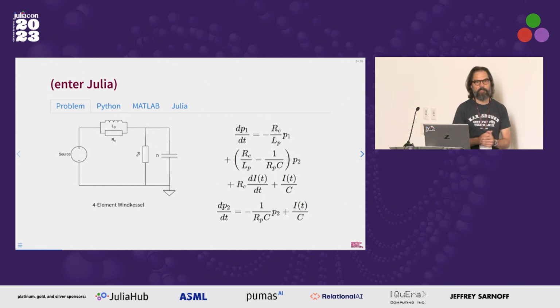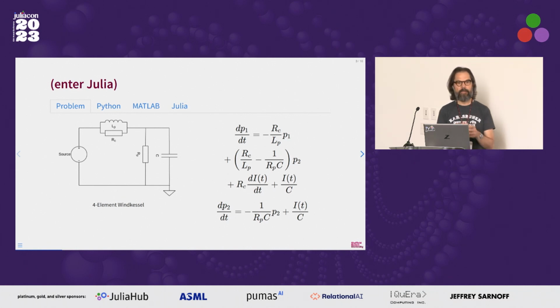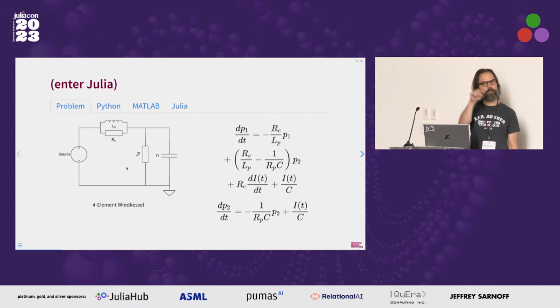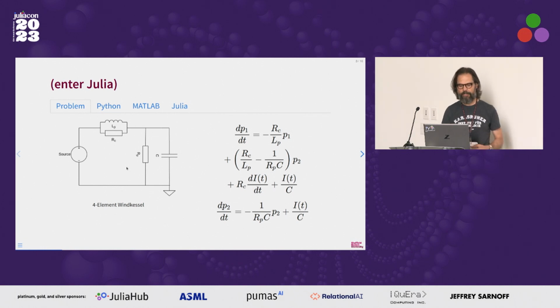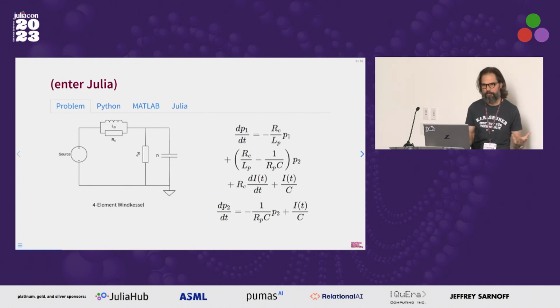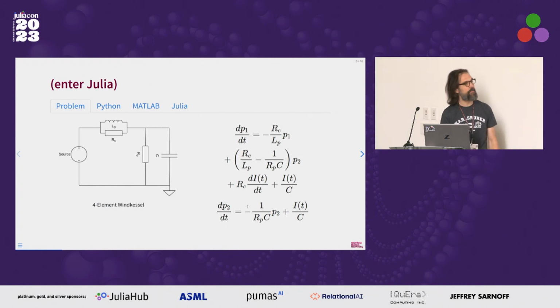And if you know a little bit about electronics, then you know that the Kirchhoff laws apply here. So you would start applying the Kirchhoff loop here. Sum of all the pressure drops around that loop is 0. In a connection here, the sum of all the current is 0, if you treat plus and minus going in and coming out. And the pressures are the same. And you build up your system of differential equations. And you do that manually most of the time. So then you end up with these 2 differential equations.